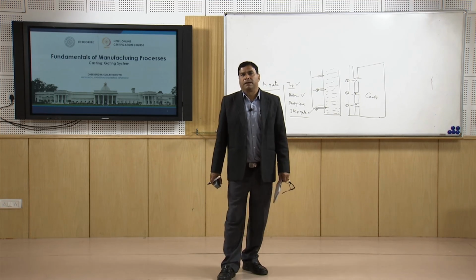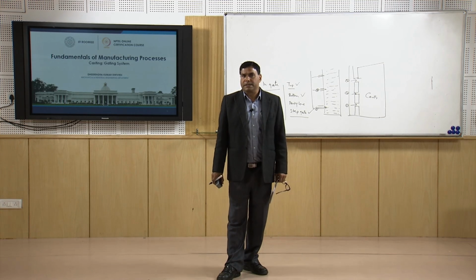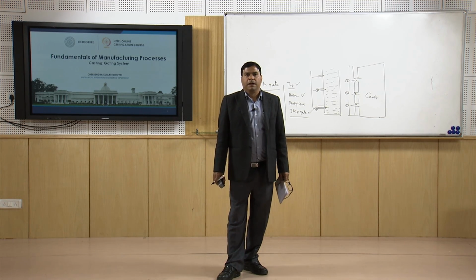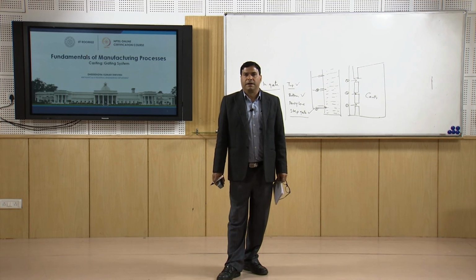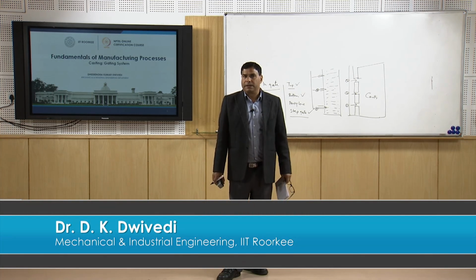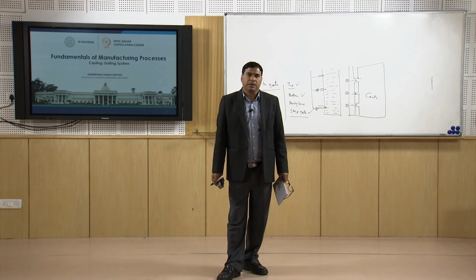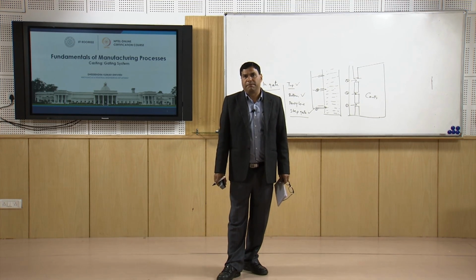In this presentation I have talked about the role of the gating systems and the different elements related to the gating systems, and the points we need to keep in mind while identifying the size of the risers, as well as the options available for preparing the different types of gates, so that suitable sound casting can be made.